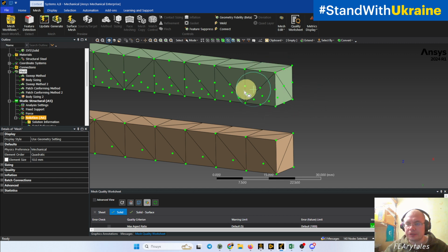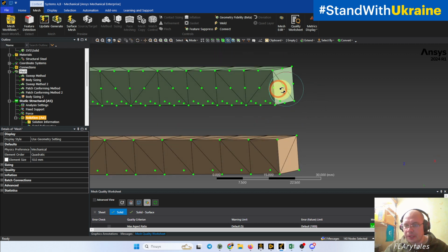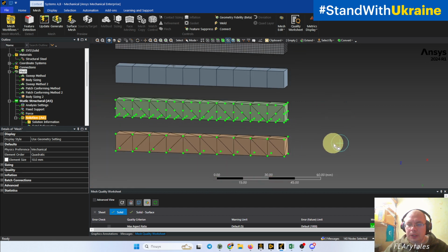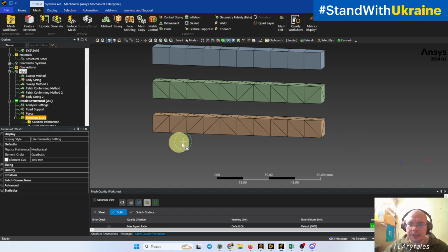nonlinear or quadratic tetra with midsides. We already talked about this. You can find information here, and we understand that for most types of element tasks these elements are not very accurate. They can be used for some types of tasks, for example thermal.